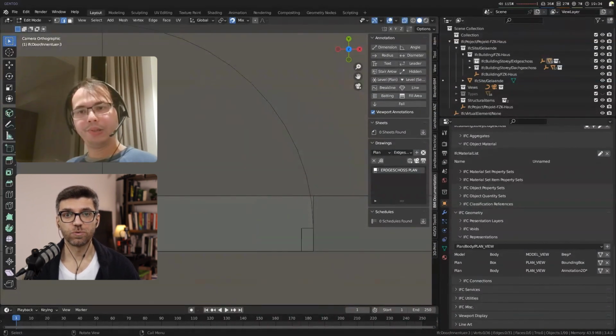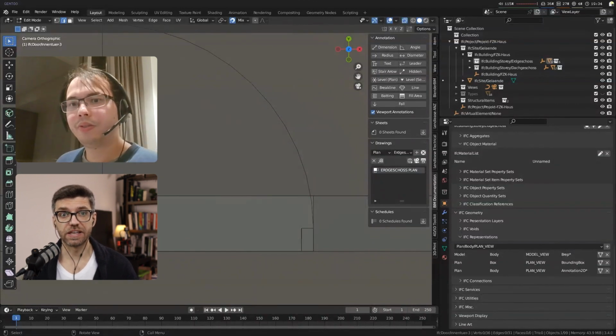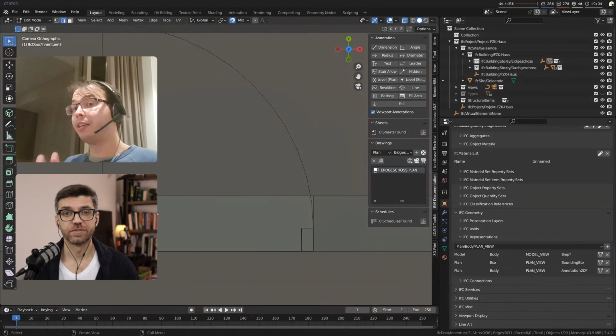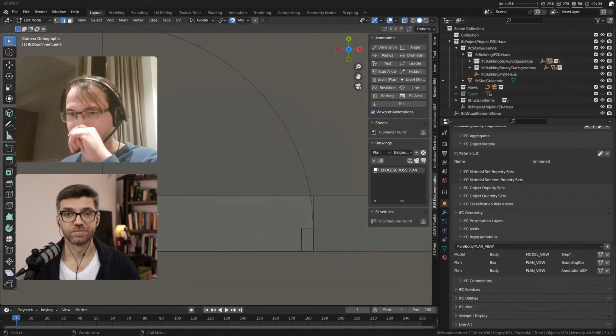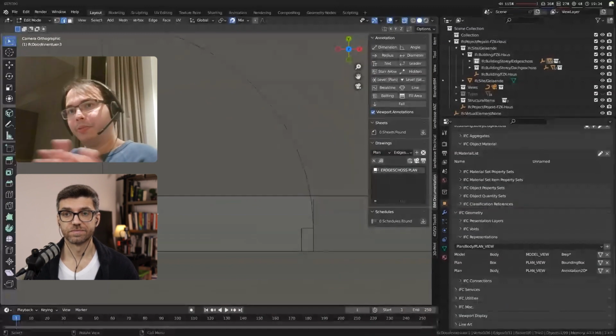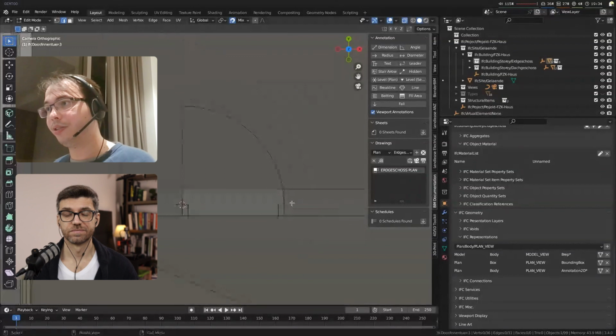But if that element, so that door in this case is an instance, this should go across all the doors and update itself. Yep. Yeah, so assuming ArchiCAD has correctly made it so that all occurrences, that's the IFC word for instance, share or map the same representation as they call it, then yes, editing this one door would mean all the doors of the same type, so they have to be the same type, right? Will have this new door swing annotation.